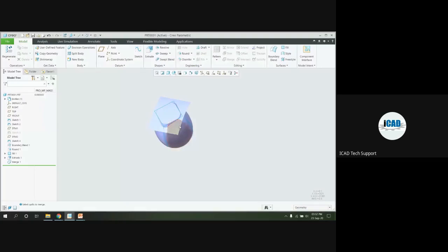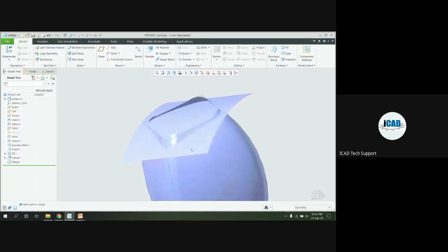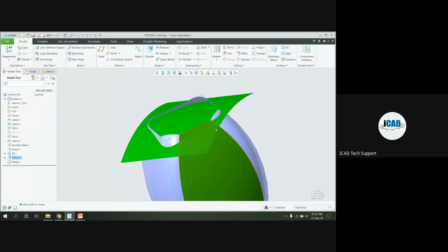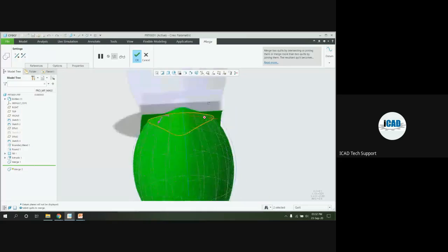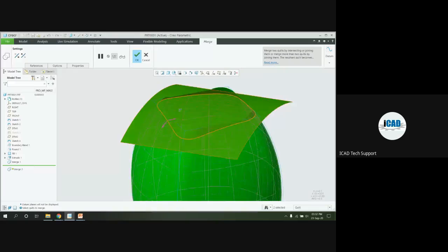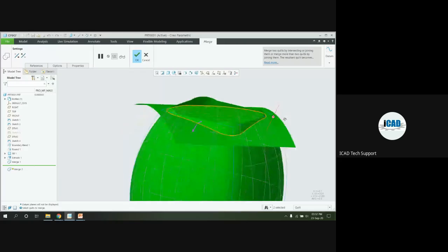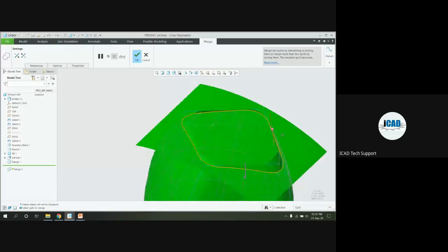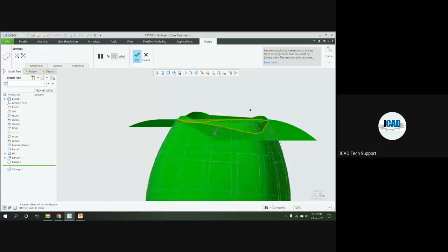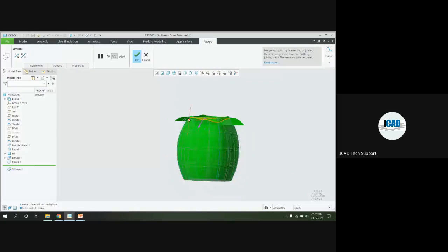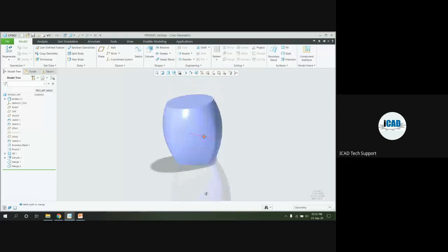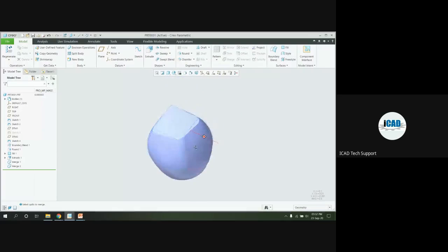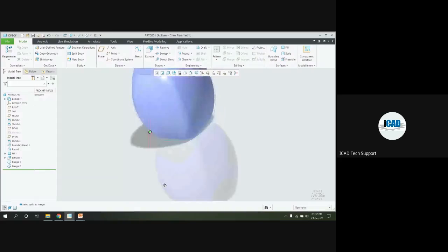You can see the intersect or join option opens automatically. And at the next step, I want to select this, and you can see the merge option opens again. Now if I click on OK, the extra surfaces, these extended surfaces from the curved surfaces, get automatically removed. You can see. So very fast and quick, by using those surfacing tools, we can create these surfaces.